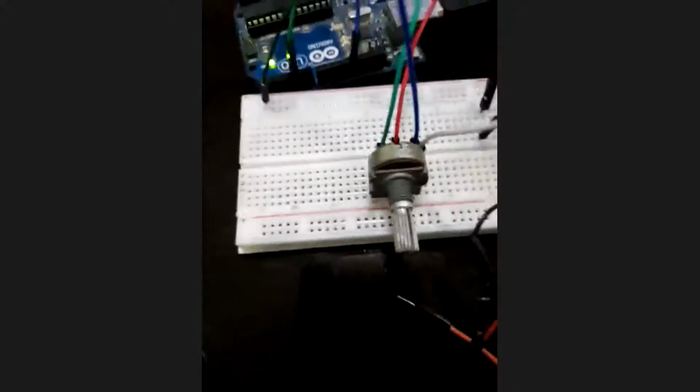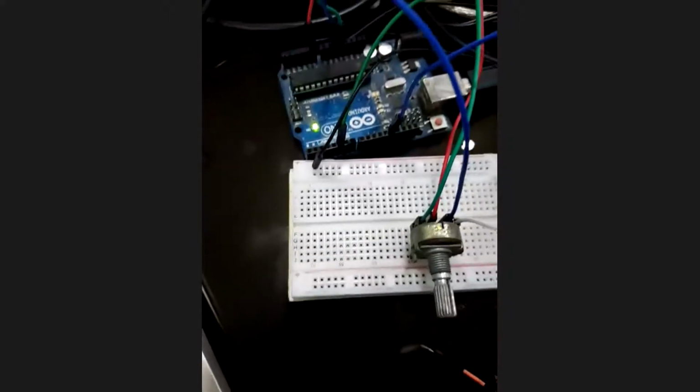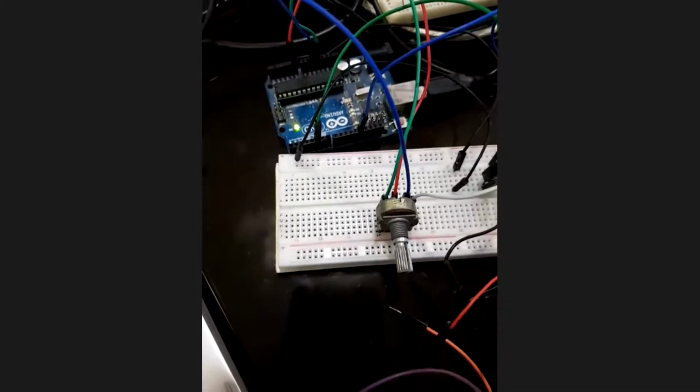The source and drain are connected to ground, and there should be a common ground here, the ground of the battery, same as the ground of the microcontroller. You should have a common ground. And the drain, one side to the motor, and the other side to the other side of the battery.